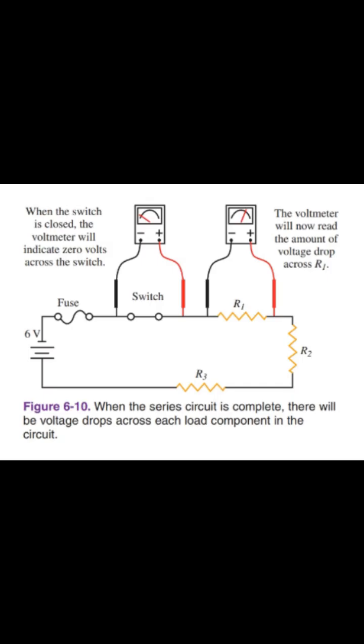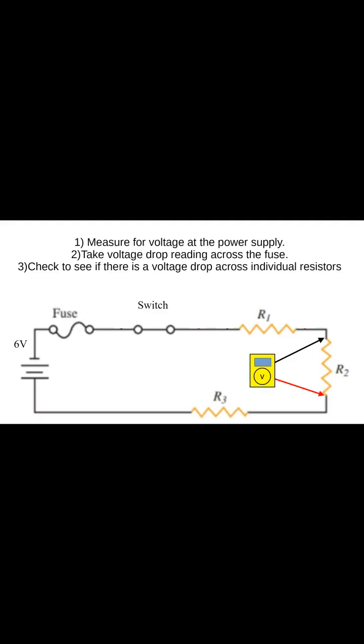With the switch pushed down in the closed position, if you take your meter and put it on each of the light bulbs, it will tell you the voltage drop of that particular bulb. If that bulb was open, the voltage drop across that bulb would read the battery voltage. In this type of circuit, there's only one path for current to flow, so no bulbs will light if you have an open in the circuit. See figure 5.4 again.